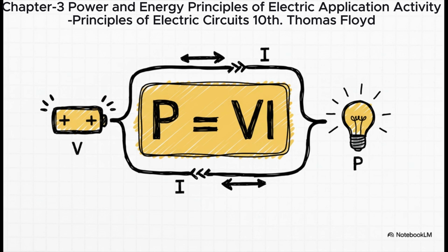And that very physical process gives us our most fundamental formula for power in a circuit, sometimes called Watt's law. The power being dissipated is simply the voltage pushing the electrons multiplied by the current, or the flow of those electrons. P equals V times I. This is your foundation. Write it down, memorize it, it's the bedrock.